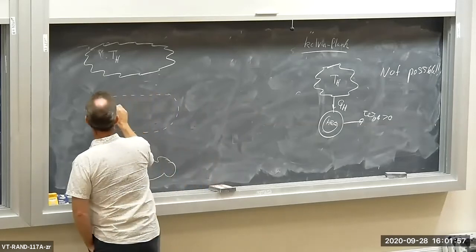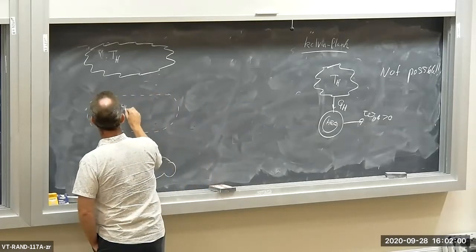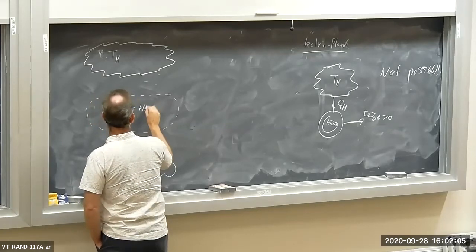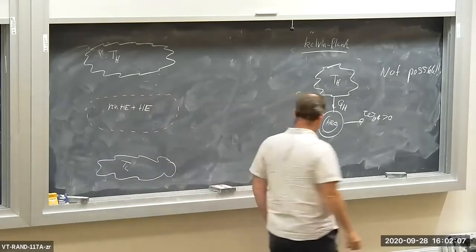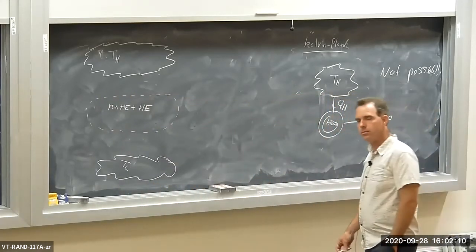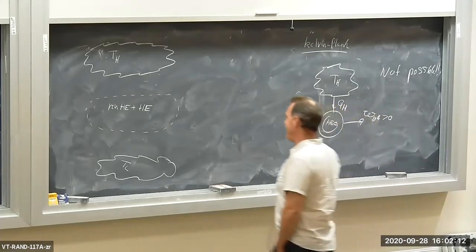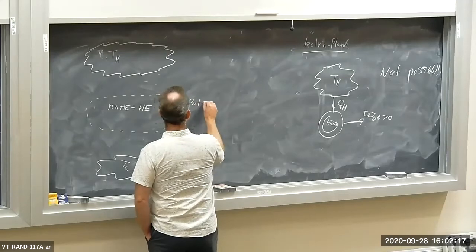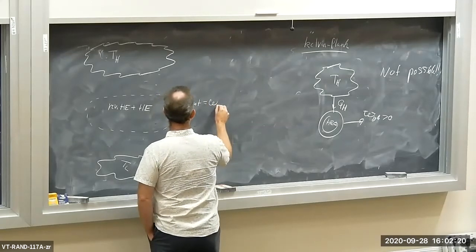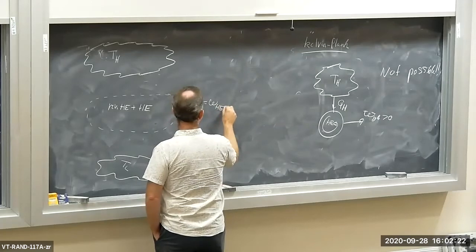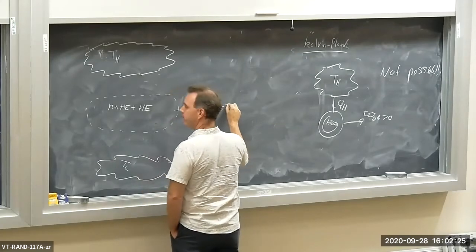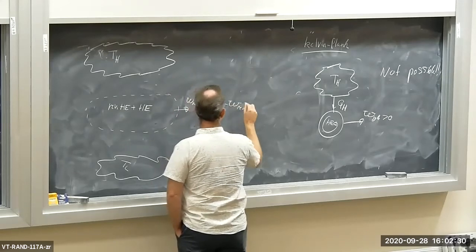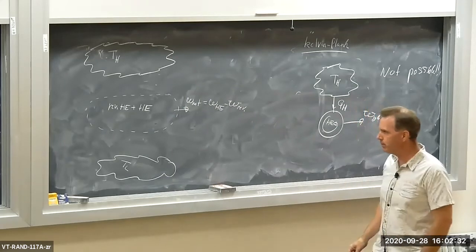So I have my reversed heat engine, reversible heat engine, plus my regular heat engine, okay? Now, the net power produced by this thing, W net, is equal to W heat engine minus that used to run the reversed heat engine, reversible heat engine. So W reversible. That's the net power produced.